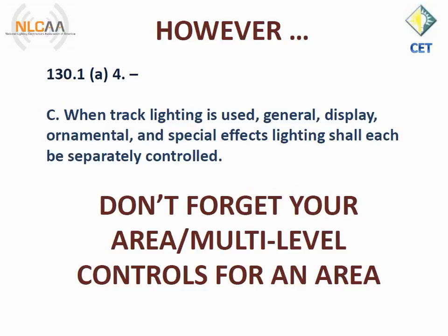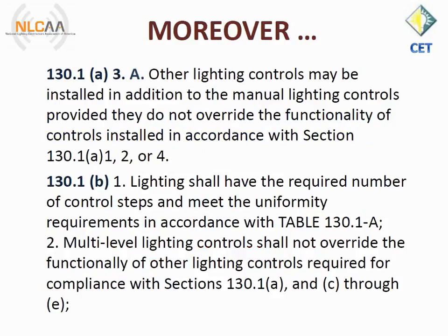Once again, different lighting functions in a non-residential function area have to have independent area or multi-level controls. Remember, lighting controls may not, quote, override each other, unquote.